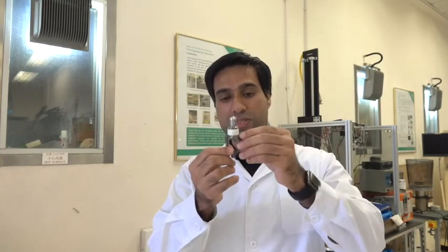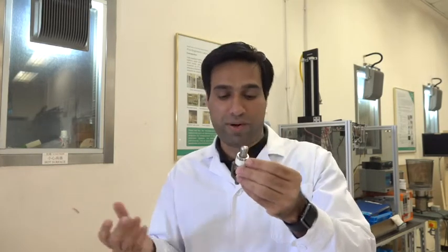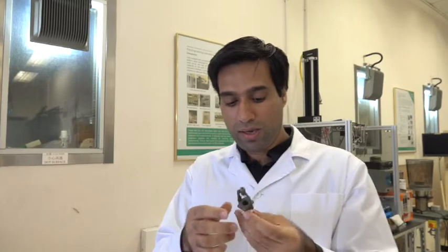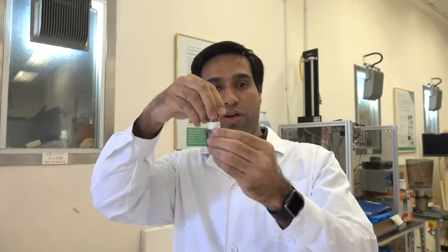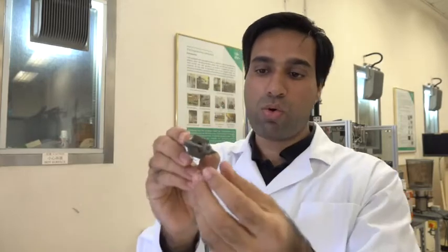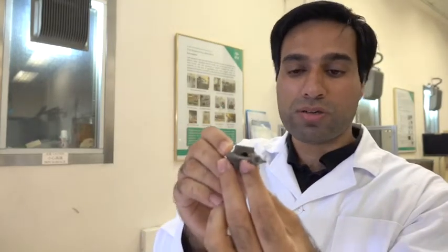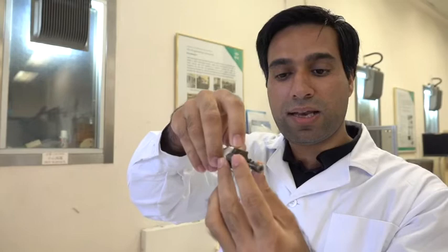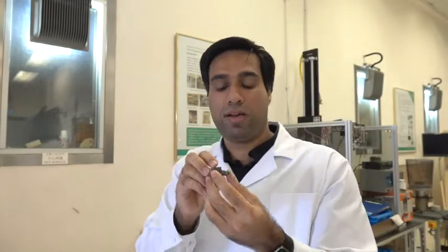So this is the water mist nozzle, which is usually installed where you want to suppress a fire. Here you see they have a mesh where the water comes out as very small droplets, and the orifice size is quite small. After the deflector the droplet size becomes like 500 times smaller.